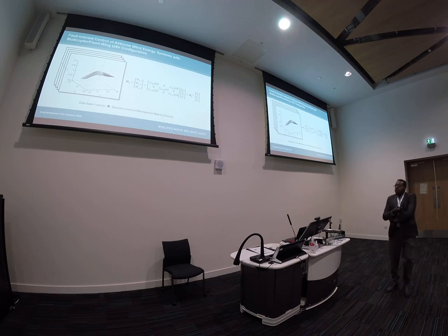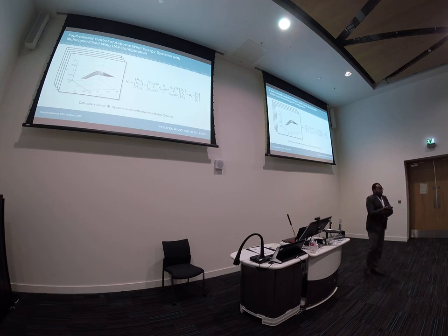Then we build a dynamic control effectiveness matrix. This matrix can translate the surface deflection to the moment of the discrete surfaces, denoted by MS. The thing about this matrix is that we will use it online. We have sensors for the airspeed, for alpha, beta, and we will compute it online to get benefit from it.